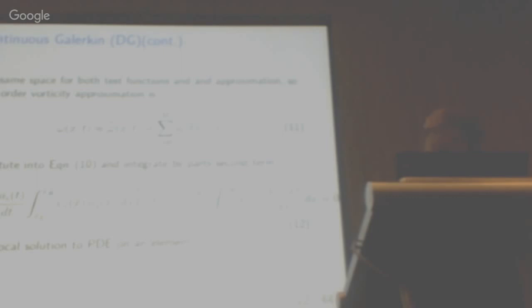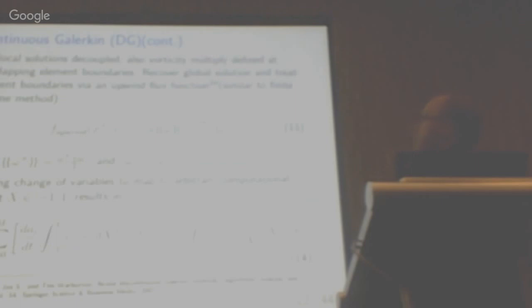Ultimately, we get this thing here, which describes globally the evolution of our vorticity. So again, here's our vorticity here. We have a numerical flux function. We have fluxes within the element as a stiffness, and then we have a mass matrix that couples things. So more DG stuff. Overall, I'm not going to go through all the steps, but from this we can assemble together a solver that breaks this into the two pieces. You have the velocity evaluation and you have the vorticity advection. And when you just simply time step through at that point with your ODE that you get from your method of lines approach.